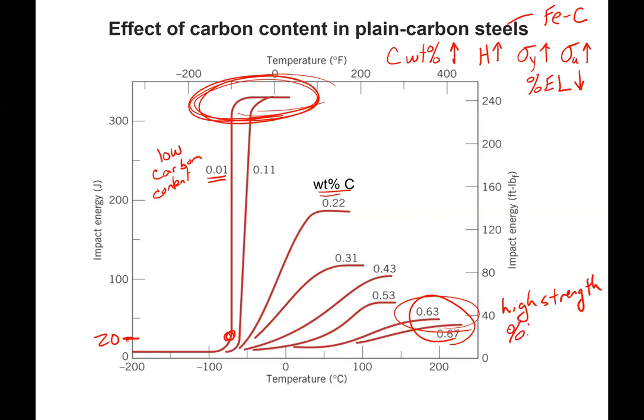But again, the ductility is going to be very low, and the impact energy for failure is also very low. So this is another trade-off, meaning that the toughness of this material is going to be very low. If we stick with the 20 mark, then maybe we could put some transitions somewhere up here, but you can see it's very high in temperature. And there really isn't much of a transition because it's already practically brittle.